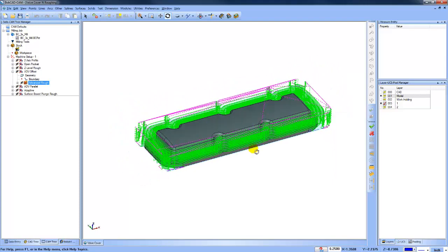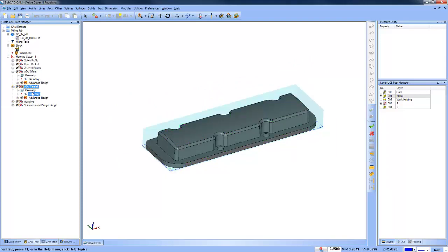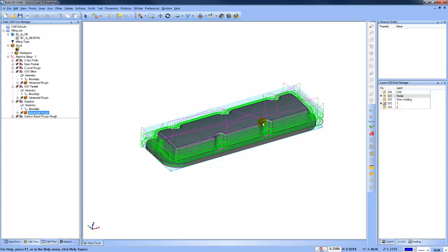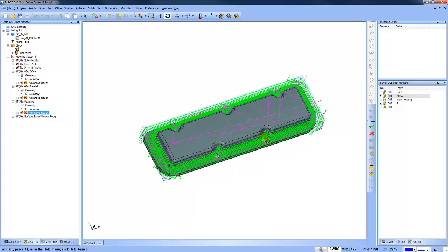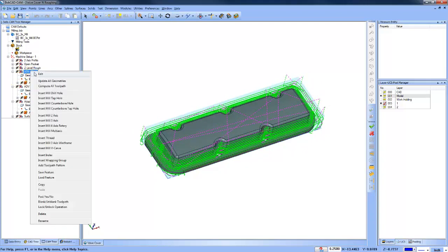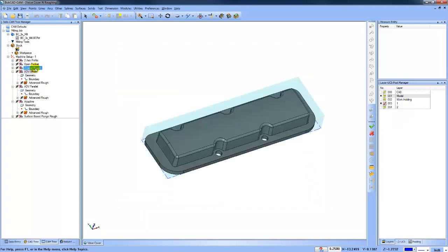Now, as we move forward from there, this is using the Mill Professional toolpath. This one's called Advanced Rough. With Advanced Rough, you have an offset style, you have a parallel style, and then you also have an adaptive style. So depending on which makes most sense for you, you may use any three of those patterns. If we go into the Advanced Rough and we go under patterns, you have offset, parallel, and adaptive. Okay, the adaptive is very similar to the open pocket routine.